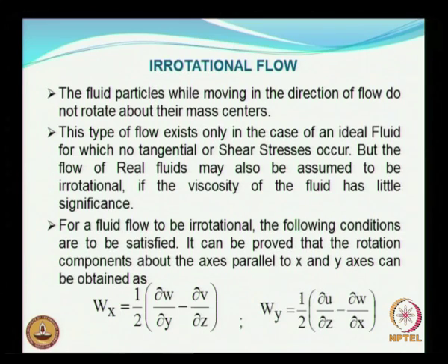So this type of flow, that is irrotational flow, exists only in the case of ideal fluid, for which no tangential or shear stresses occur. But if the viscosity of the fluid is very small or does not have much significance, then this kind of flow can be assumed even in the case of real fluids.